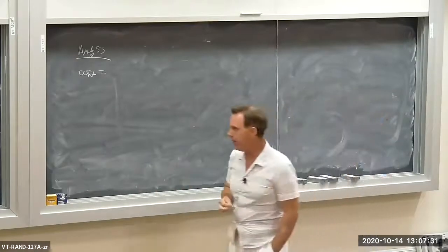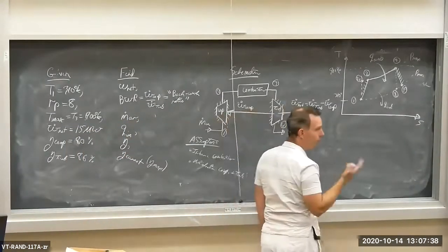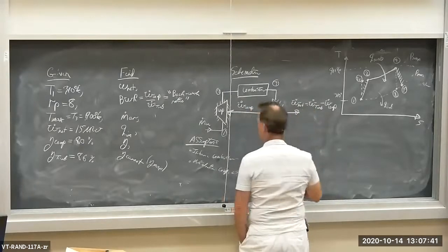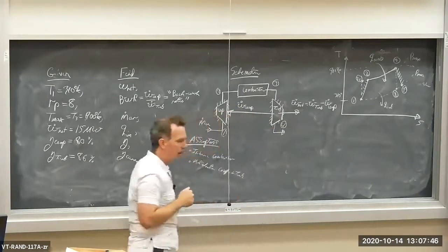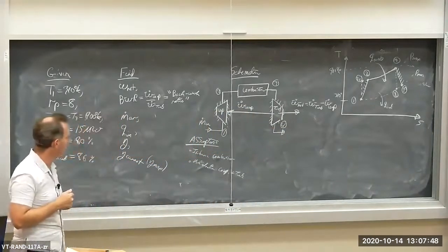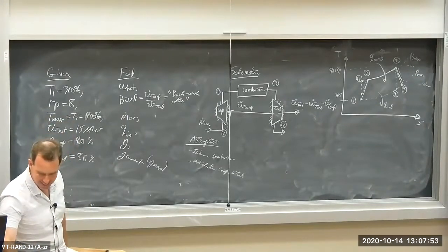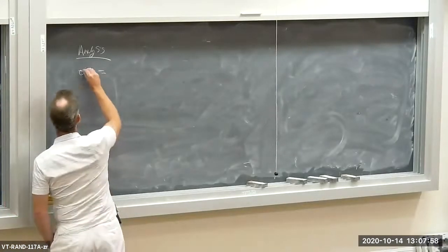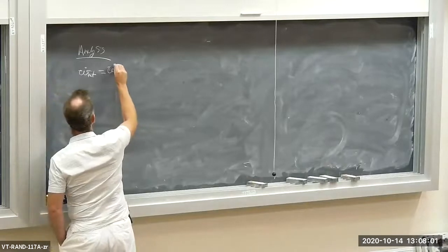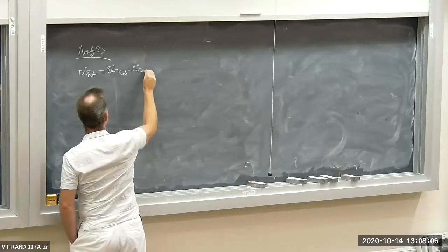Now, W net is the difference between the turbine and compressor power, or work per unit mass. So assuming the m dot is all the same throughout the cycle, then the difference between the compressor and turbine power is the net. Okay? So let me write here, W dot net is equal to W dot turbine minus W dot compressor.